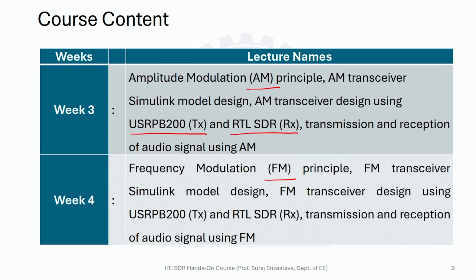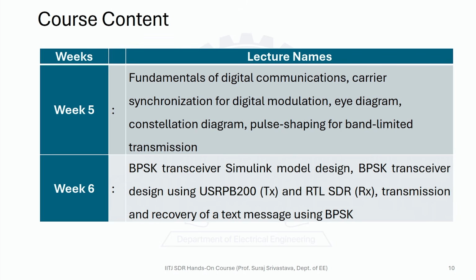Now when we come to digital modulation, the information signal has to be in digital format, in binary form. If the digital signal is already in binary form, we can directly use the digital communication systems or digital modulation techniques. But if the signal is not in digital format, one can still convert it into digital format using the well-known sampling, quantization and encoding method.